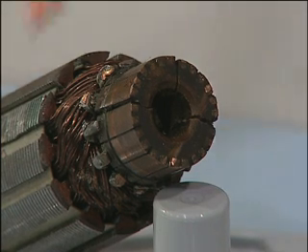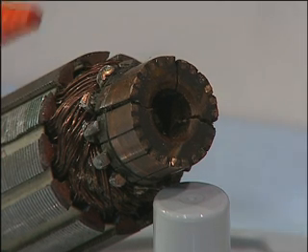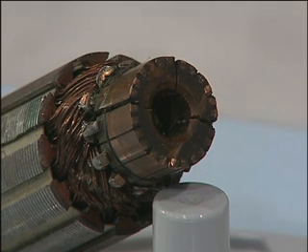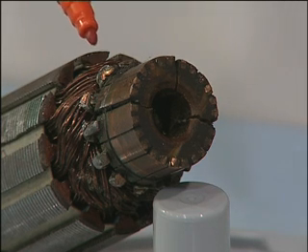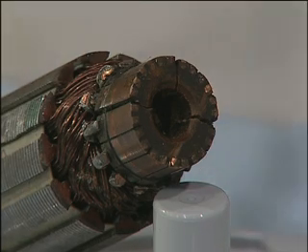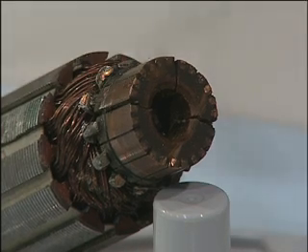This whole set together is called the armature. So, the armature consists of the core, and that is also laminated here, again because, as we were explaining during the time of the transformers, the laminations are used to reduce the eddy current losses. This portion is the coil ends which are joined to the commutator segments. The brushes will come in contact at this copper surface of the commutator segments.